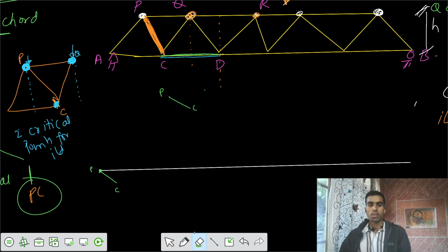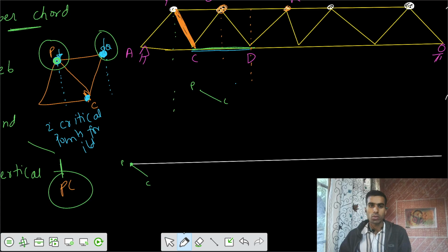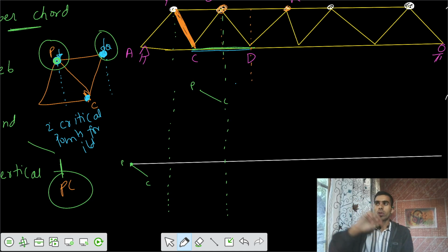So I would say the direction for that ILD would be in the same sort of nature. Let's say the ordinate, we have the critical location. What we derived is the critical location. We say one of the critical locations is point P and one is Q. If the point P is the critical location, that means up to the point P we have one ordinate that's critical, and after that we have point Q, one more critical point. So we only have two critical points. Once you have the two critical points, you join them by a straight line, and then you connect them to the ends such that you make an ILD.